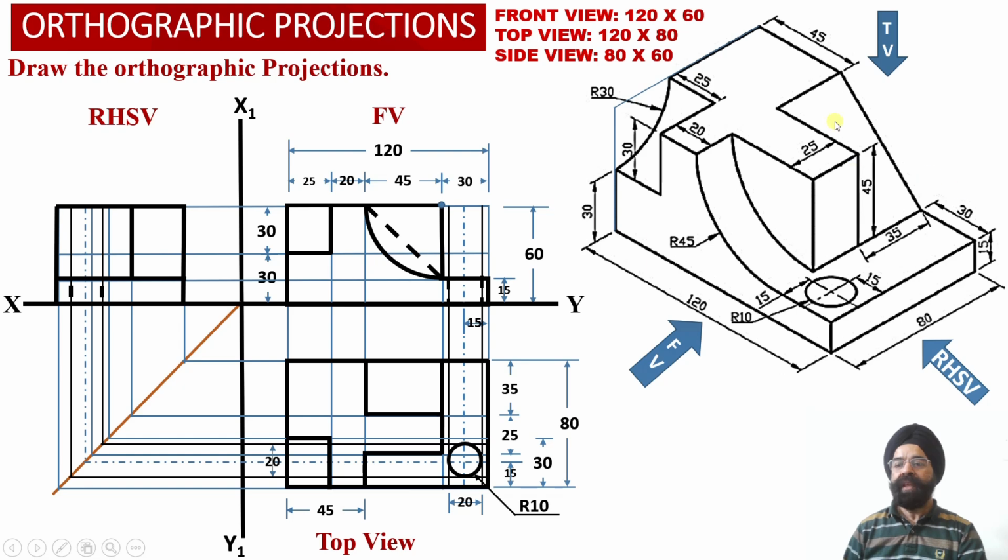Next we have this inclined rectangular surface. Since this rectangular surface happens to be inclined with respect to the profile plane as well, the projections of this inclined rectangular surface onto the profile plane will be obtained as apparent shape rectangular projections in the right hand side view projections over here. So these are apparent shape projections corresponding to the inclined surface, which is our element number 4 over here.